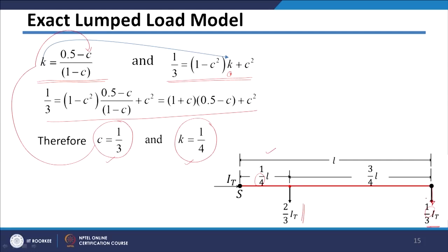And if you calculate the voltage drop and the power loss using these two lumped loads, it will come out accurate. It will not be like lumping at one location, where we are getting different locations for power loss calculation and different locations for voltage drop calculation.